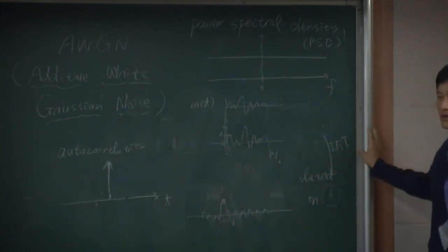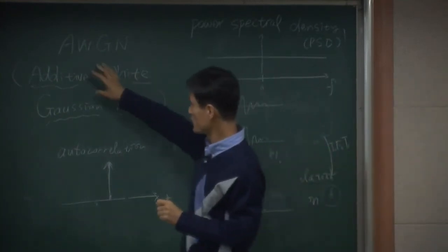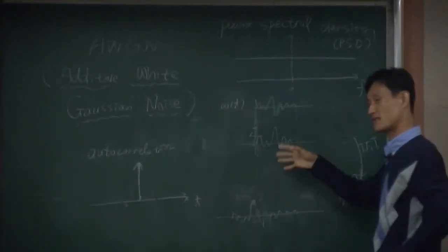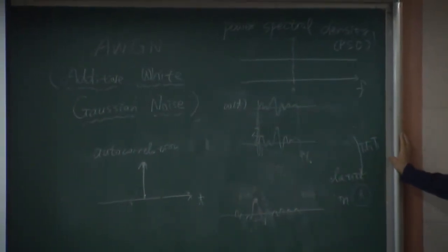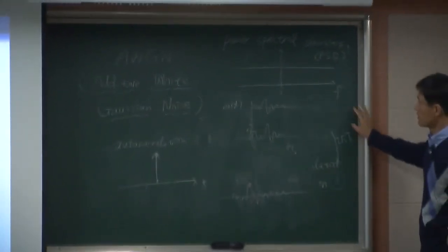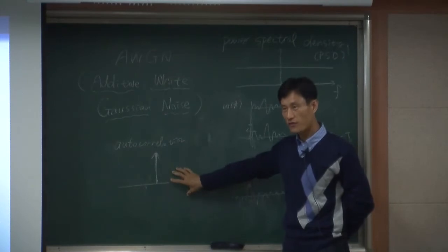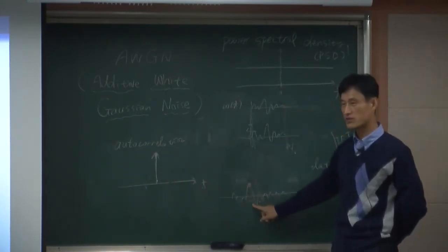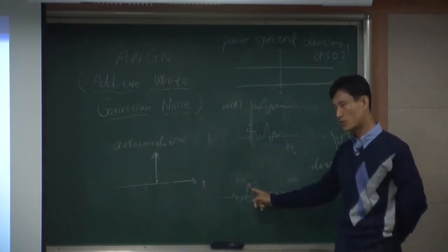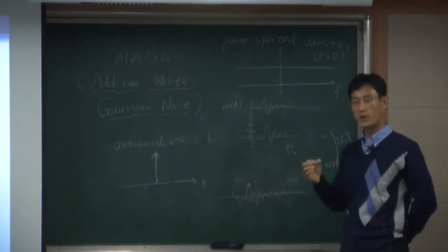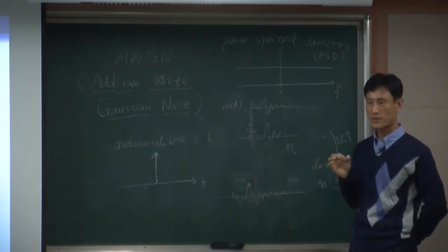It's very important. Okay? Very important. Everyone has probably heard about AWGN, but you need to understand this whole thing. That's the exact meaning of white. We have this power spectral density, we have this autocorrelation, so therefore we have this relationship. Between two different noise samples, the correlation is always 0. Always.